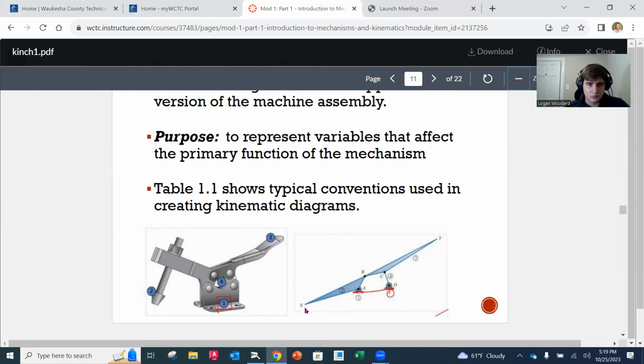Additionally, you're going to notice that down here is point X, and that is going to refer to the clamping edge in relationship to what we're going to call the frame, which is going to be the points that don't move. And notice here that X is out there. As the designer, you may even be concerned about another point of interest, which may be the top portion of this clamp part. As this rotates up, you don't want it to interfere with the handle side. So that might be another point of interest.